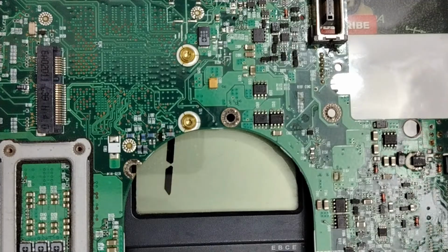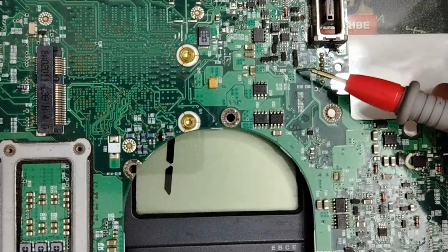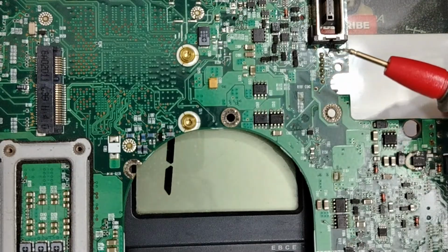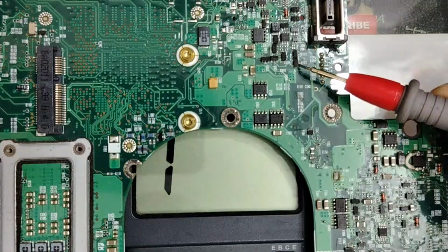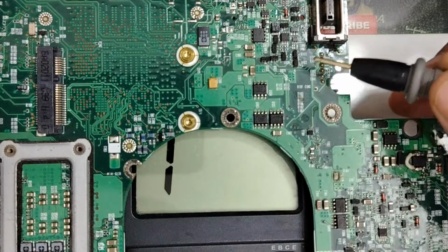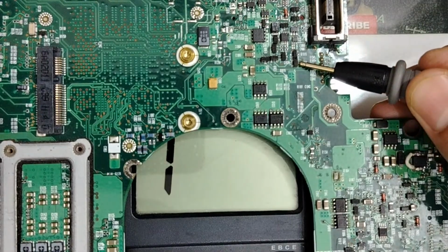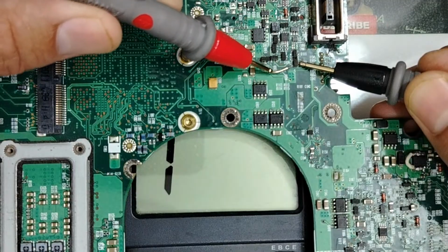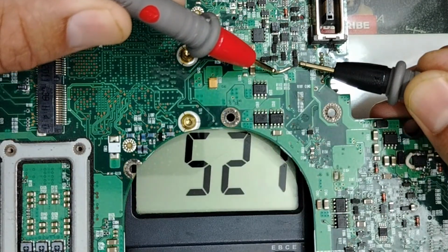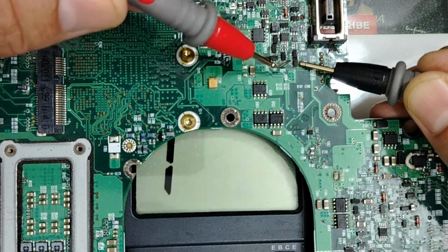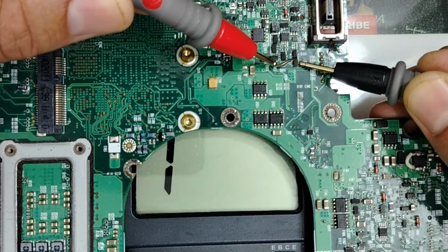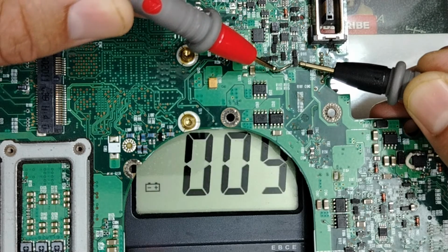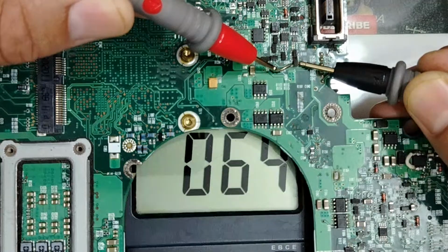So, my friends, we checked diodes, and as I told you, for MOSFETs it's different. Let's check this MOSFET, for example. If I put one probe here on this side and check this pin from source to drain, we get a reading. From source to drain, we get a reading. But from this gate to drain, nothing. Do you see, my friends? Nothing. Here we get, oh, wow, zero. Why? Is it a short?